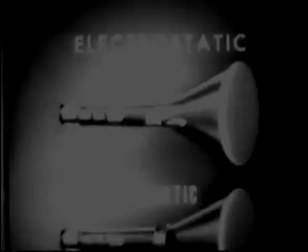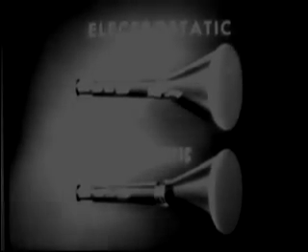And in the first two pictures of this series, you saw in detail how the timer, transmitter, and receiver did their jobs. In this film, we'll see how the indicator functions. Let's take a look behind the panel and see how this typical A presentation is formed. This scope picture, as well as all others, are created by a special type of vacuum tube called a cathode ray tube. There are two basic types of cathode ray tubes: the electrostatic and the electromagnetic. These tubes produce all the scope pictures in radar. Let's see how they operate.